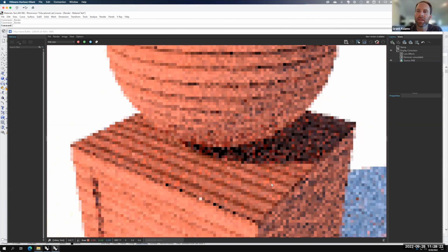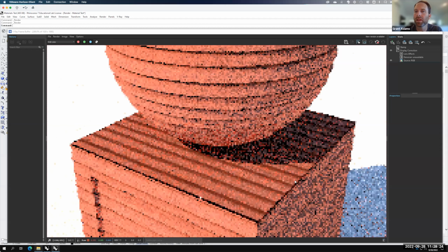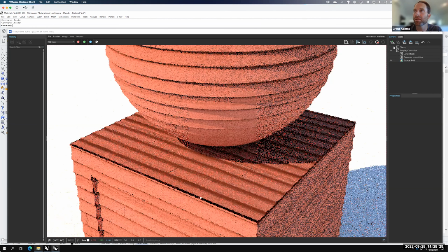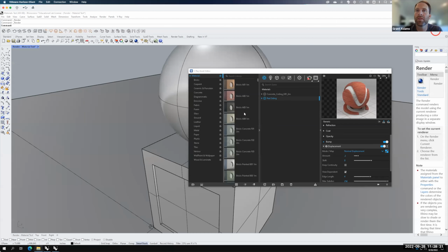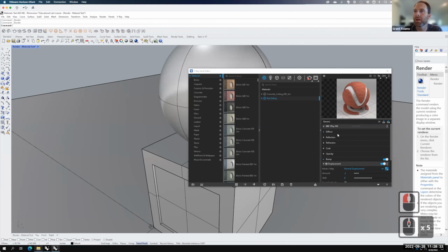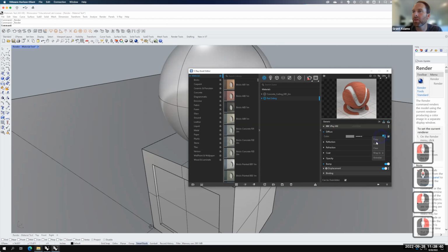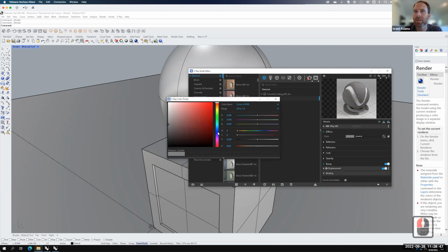Now, one of the interesting things that we can actually do on this is we can eliminate some of the photorealism of it and then change the color of the siding. So once I have this set up here, I could come in here and under diffuse, I could actually clear the photograph away, but I'm still getting the texture underneath. And then I could change the color to some different color. So I could say, what if I painted the wall in a light blue?